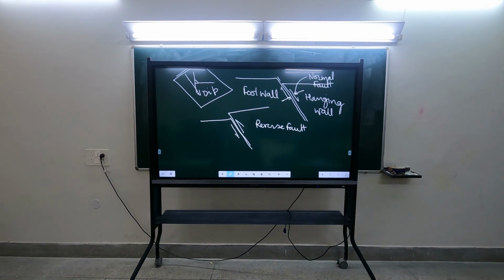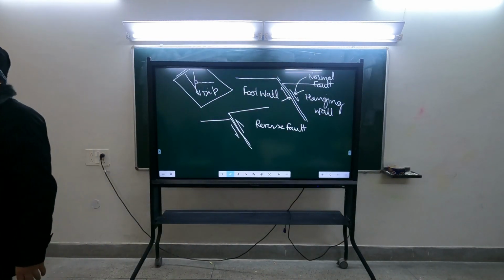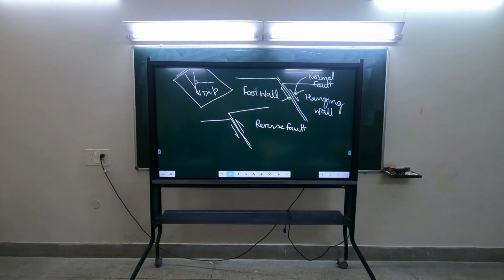But because it is brittle material, what will happen? Till it fails, it will go on taking the loads, and suddenly it will fail. And when it fails suddenly, it will cause a jerk. And that jerk travels to my site. And it is not only one jerk, several jerks. One jerk will occur, and as I said, that rupture is like an unzipping failure.